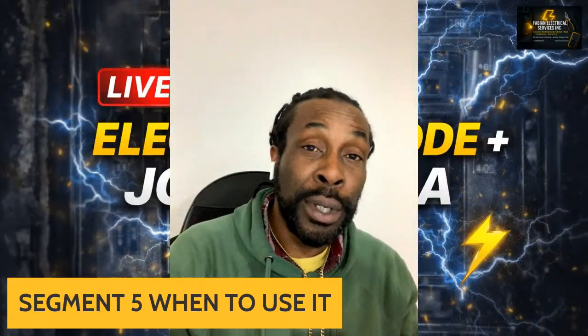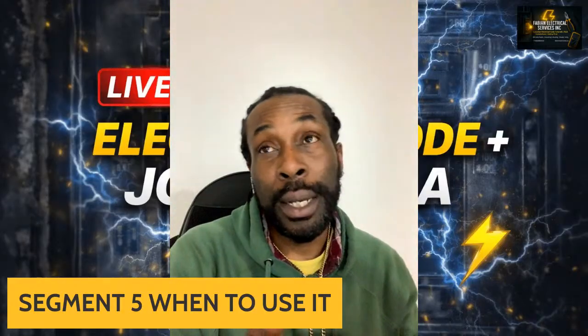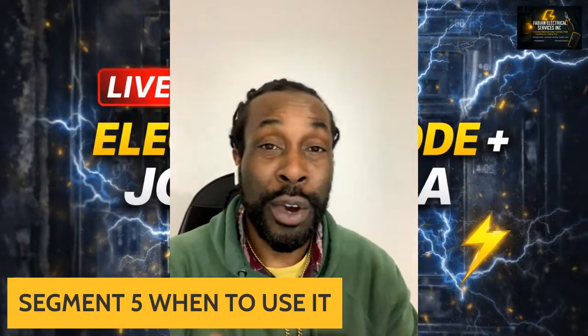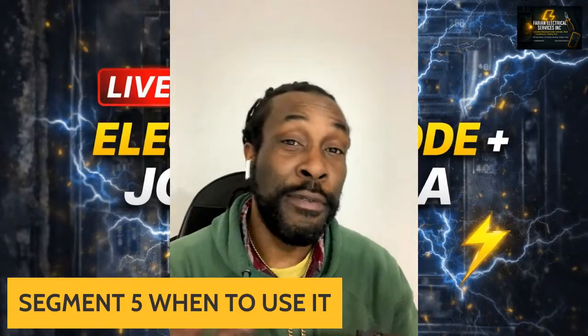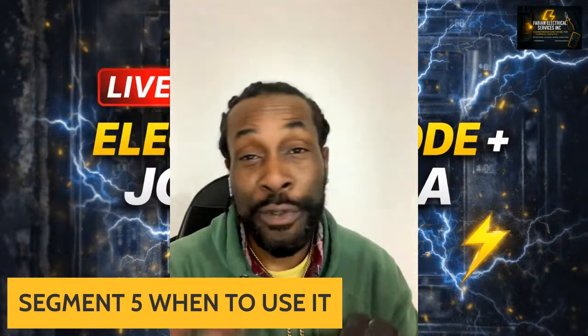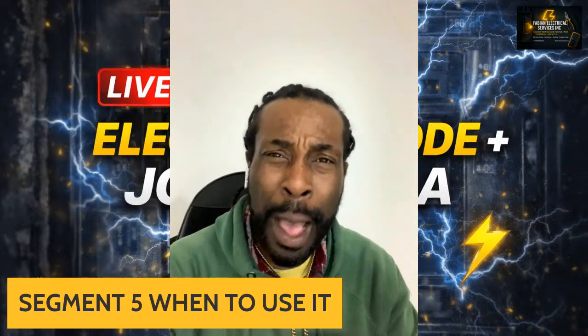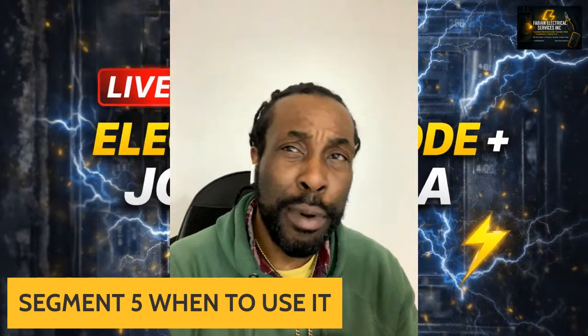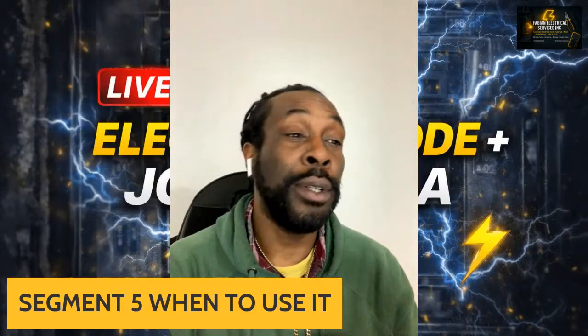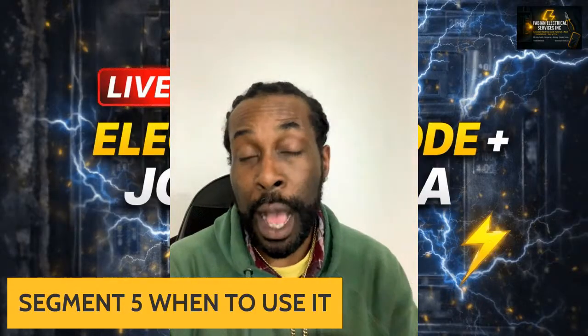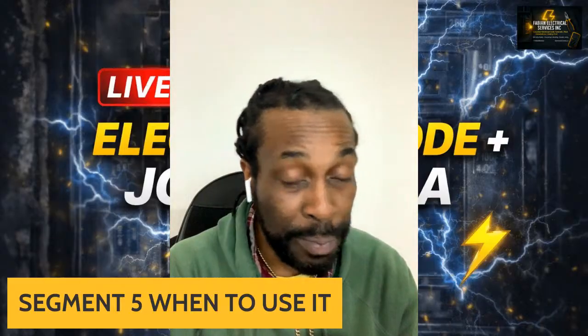In a Siemens panel you can install an Eaton, but it is not correct because it voids the warranty. You can fail inspection. That's what makes you fail inspection. Having a Siemens breaker inside of an Eaton panel for your final, you are going to fail. It is not supposed to be inside of there.